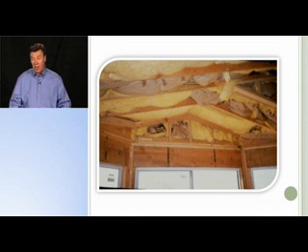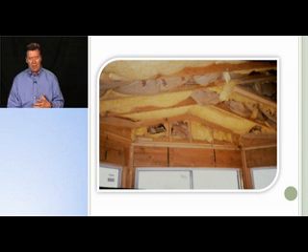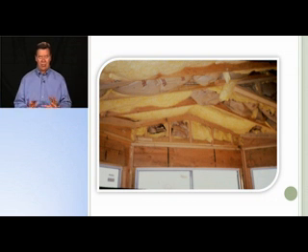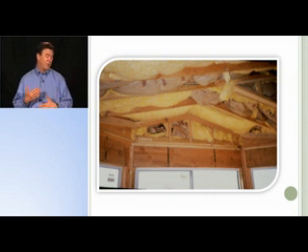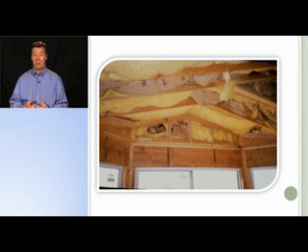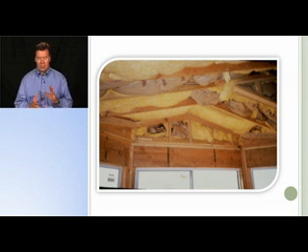Now, when we look at what that looks like in the real world, oftentimes when insulation is installed, it's installed very poorly. Doesn't work well. For example, here you can see that the fiberglass insulation is just crammed into this sloping roof, and it's not going to work very well because when the insulation is compressed, it loses some of its ability to trap air, so its R value drops and we don't get the performance. So when we talk about buildings looking good on paper, they may have R30 insulation, for example, like we have here in an attic area or sloping roof area, but it's not going to perform like that because it's compressed.